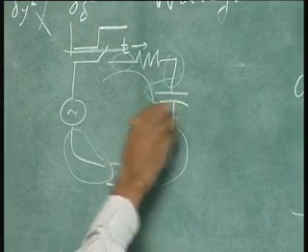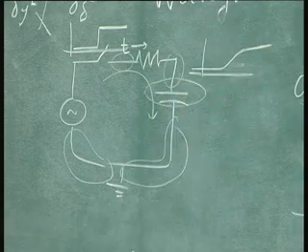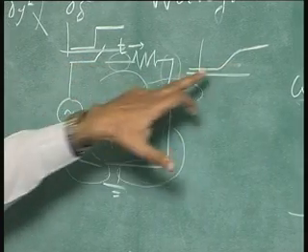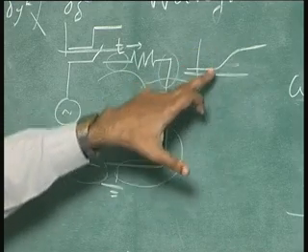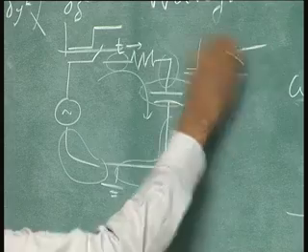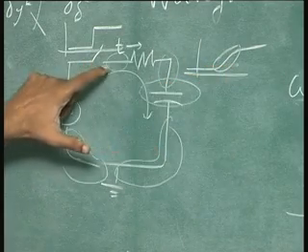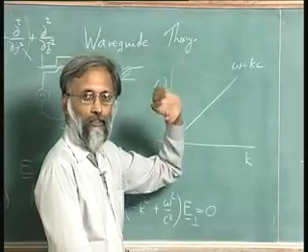But out here, it may very well be that the signal will look like this. That is to say, the fact that the switch closed was not a very sharp start in the current, it starts gradually. There is a rise time to the signal. And this rise time comes because the wire is not carrying all frequencies with the same velocity. But this particular solution we have is a special solution.